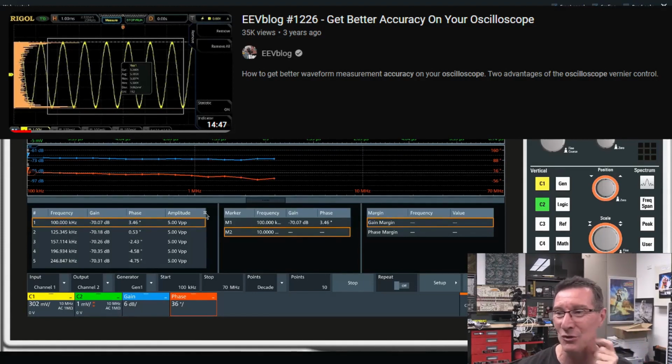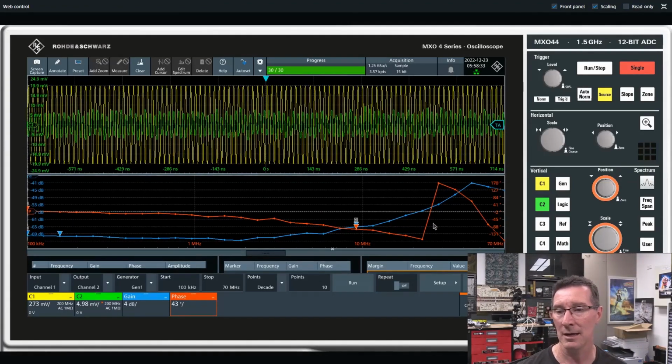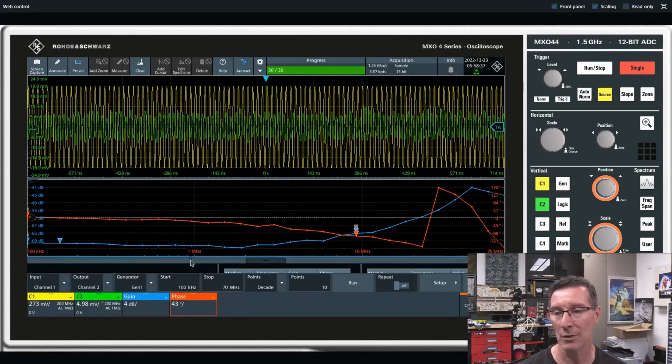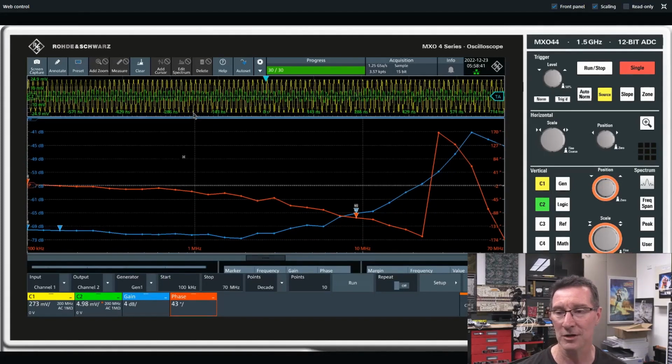This is really cool. This is a very good frequency response analyzer. So we're looking for the phase response to actually reverse here. Oh, yep, there it is. Hey, that's totally expected. That's normal amplifier behavior, not just a differential amplifier. So expected that. But once again, phase doesn't mean anything here.